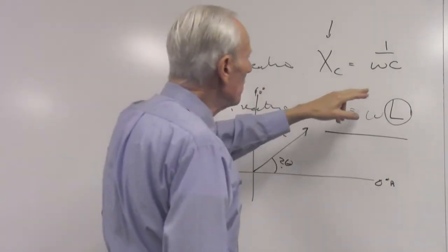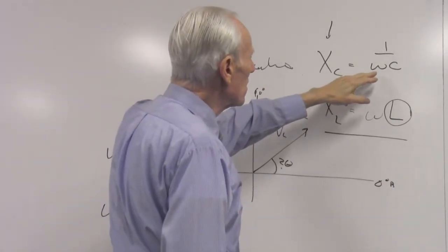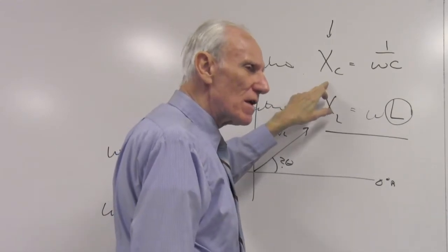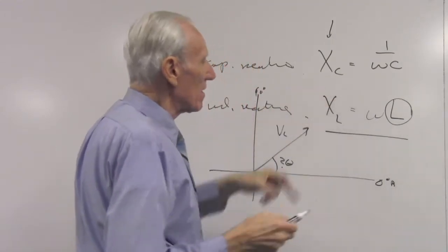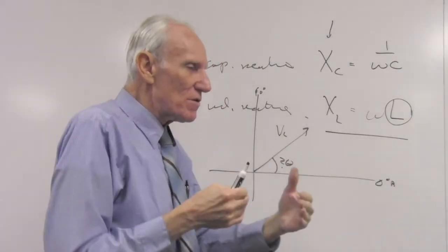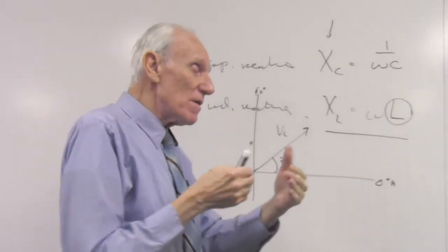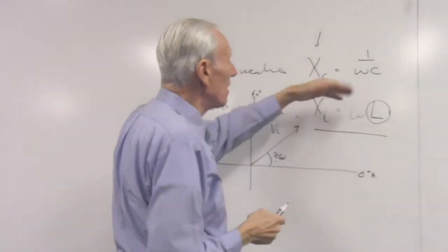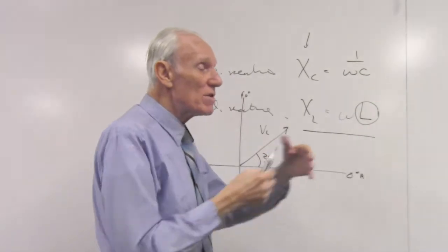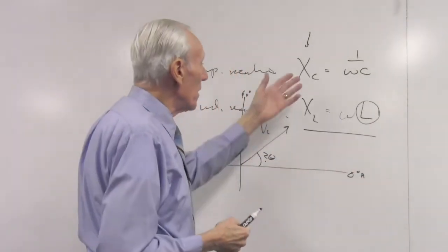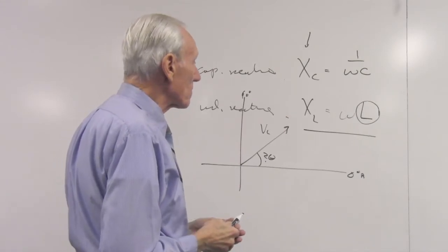And again, you can see here that as the frequency increases, this gets smaller. That's interesting. And what that practically speaking means is, if you have a capacitor and you charge it up and discharge it really fast, it doesn't have much time to charge up and discharge, so it doesn't do much to the current. So we have an inverse relationship. The higher the frequency, the less of a blocking effect the capacitor has on the circuit.